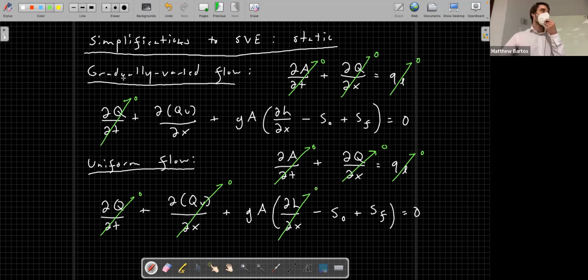So in summary, for uniform flow, we have that the bottom slope is equal to the friction slope, or in other words, the gravitational force matches the frictional force exactly and is constant in time. Okay, so that's when you can apply Manning's equation. That's my conclusion for today. Thank you.